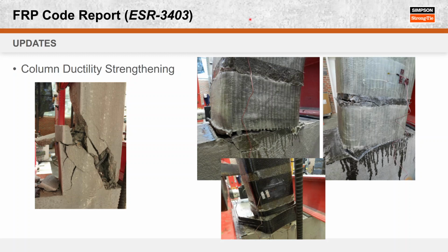Yeah, well, I think about this testing, column ductility strengthening. So for column ductility, what are we strengthening? Like, what strengthening type is this? Is this like a shear? This would be like flexural. We also did shear. Is it like combined axial and bending? I'm not sure if they added axial load on these specimens or not, but they racked them back and forth. So it's basically confining for it.